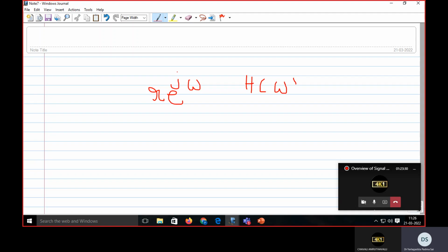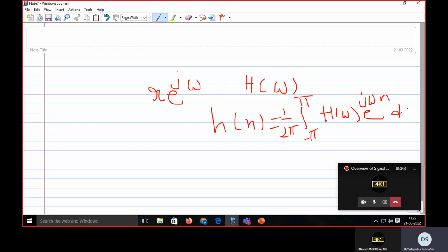According to the Fourier series method, what you have to do is calculate h(n). h(n) is the inverse Fourier transform, 1 by 2 pi, integral from minus pi to pi of H of omega e power j omega n d omega. By using this equation, we are calculating h(n). Okay, h(n) is having an infinite number of samples.